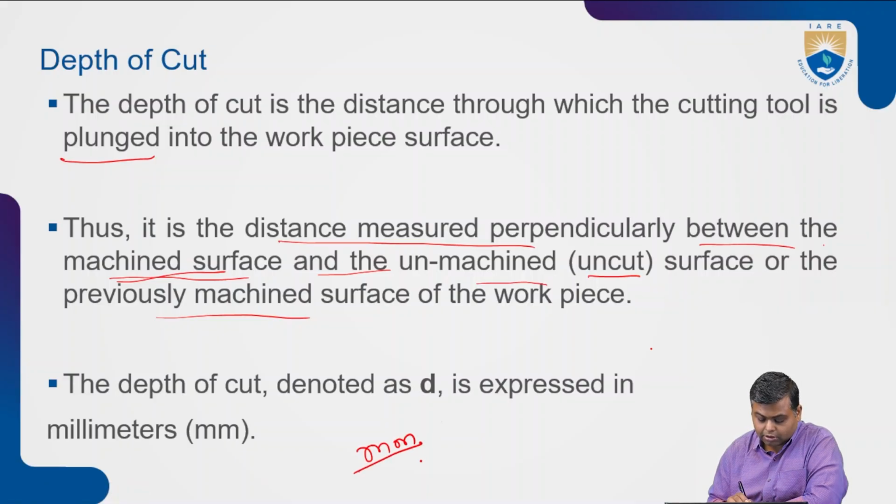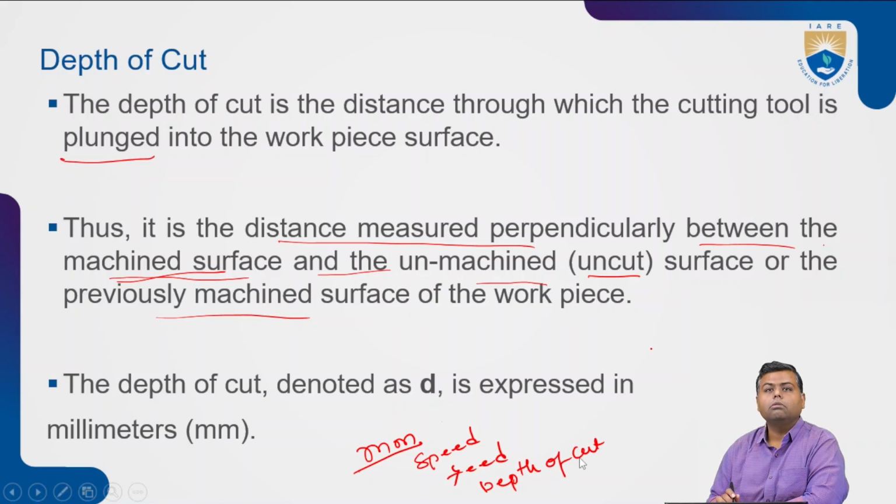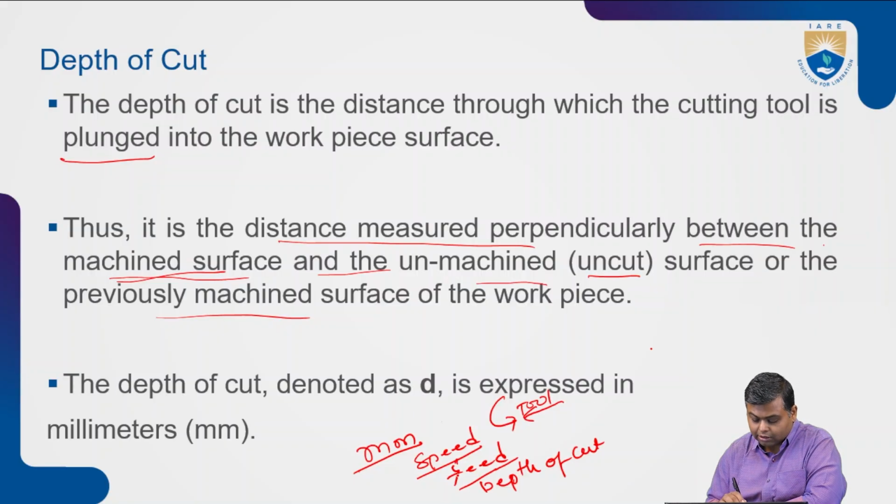So speed, feed, and depth of cut: all these three things are the major parameters which are used when the machining process is carried out. Speed, that is revolution, is very important, as well as the movement of the traveling of the tool tip along the work surface. Now, feed can be delivered in two terms, that is mm per revolution or mm per minute.